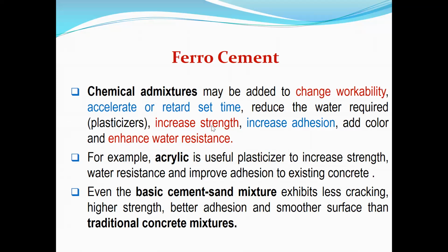And sometimes admixtures are used to increase strength and adhesion. You know that the cement paste needs to adhere to the structure or the wire mesh, so some adhesive quality is to be imparted. You have seen the picture of the water ride. Some admixtures are used to add color, and if you make a ferrocement structure which should be water resistant, a water resistant admixture may be used.